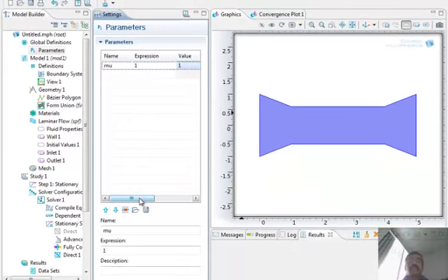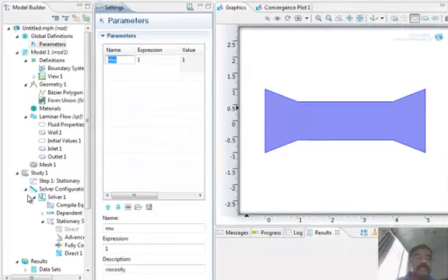And you can put a comment here if you want to say what it is. Viscosity. Oops, where is it? Okay. So I have defined the symbol mu. So when it solves a problem, it comes to this table, picks up the value. Okay, that's one thing. The other thing I want to do is in the study stationary,